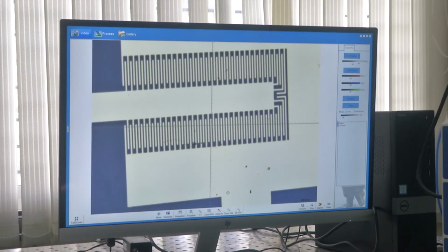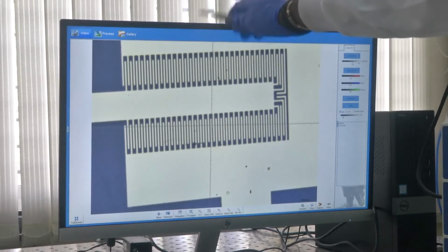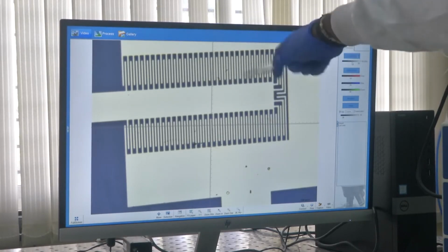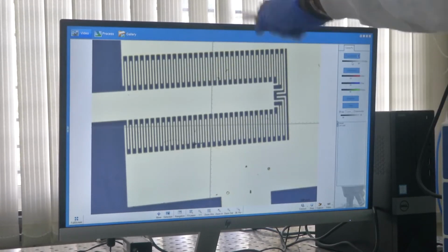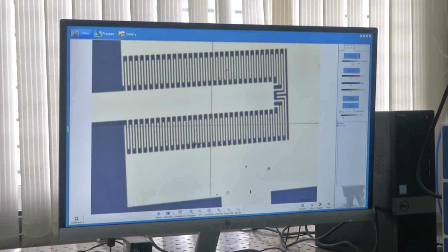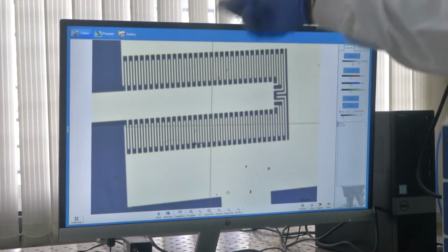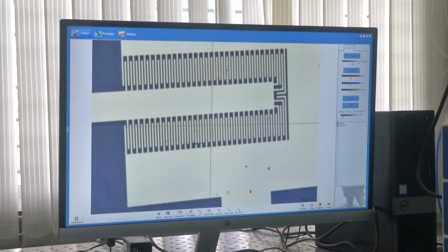Okay. So these can act as sensing layers for multiple purposes. Because by default, if nothing is there on top, this will be an infinite impedance, right? Ideally. So if some material, some analyte is kept on top of this electrode, it will cause an electrical connection. Through that electrical connection, we will be able to measure the resistivity of the electrode. So for different biological material, we will have different resistivity, and with the same biological material in different conditions, there will also be different resistivity. This can be used as a biomarker for detection. That is how this type of biosensor works.